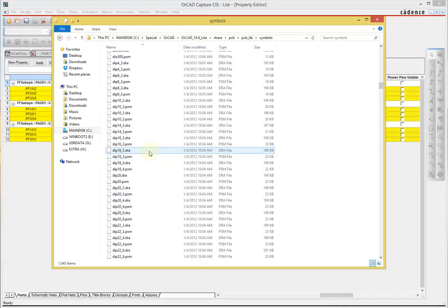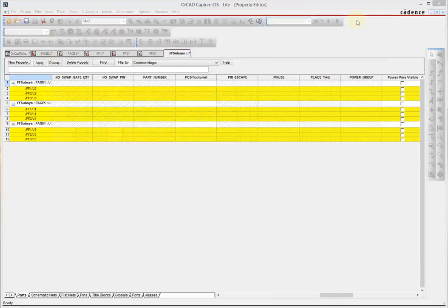Let's take for example that you were in a different situation. Hypothetically, suppose that the part that we need is a 20 pin dip, right? Will you write down DIP20? Will you write down DIP20_3? Will you write down DIP20_4? Will you write down DIP20_6? Which of these parts do I pick? They all have 20 pins. So I need to look at it. And unfortunately, to do this, I have to prematurely open the PCB editor in order to be able to look at the footprints.